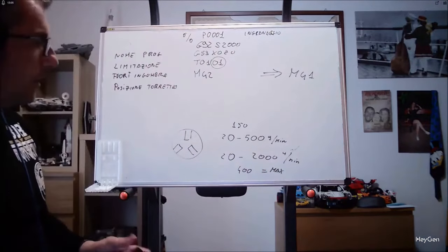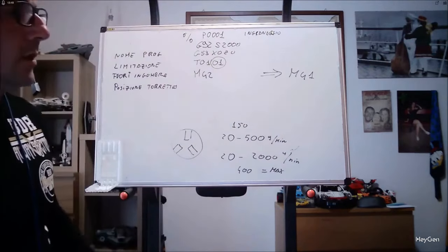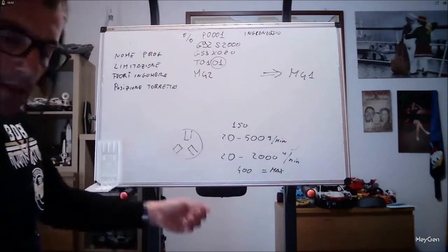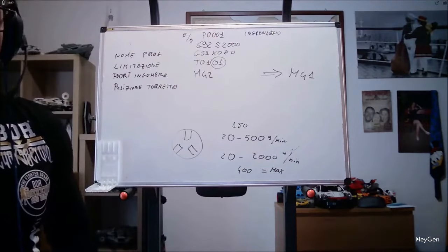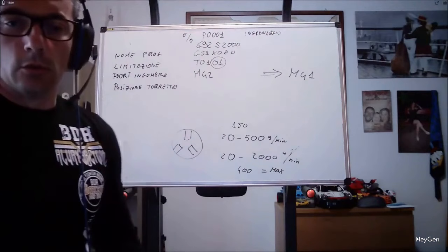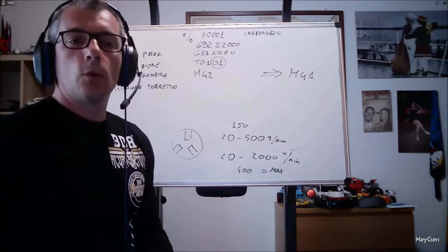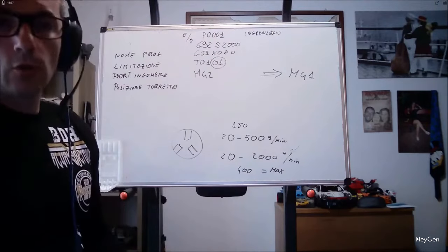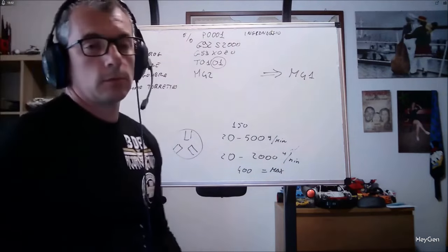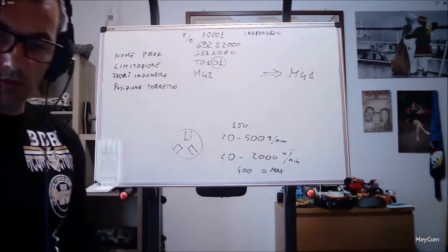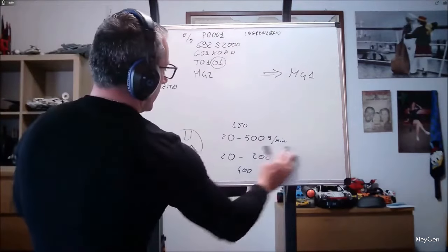So if you are used to working with aluminum, you work in range 2. If you are used to making heavy cuts in cast iron or very hard materials, you work in range 1. This will be your experience, and especially the type of work you do. So, gear engaged, range 1, M41, you are on an off-road vehicle going uphill. In range 2, you are in a nice sedan racing down the highway. This is the substantial difference between the two ranges.